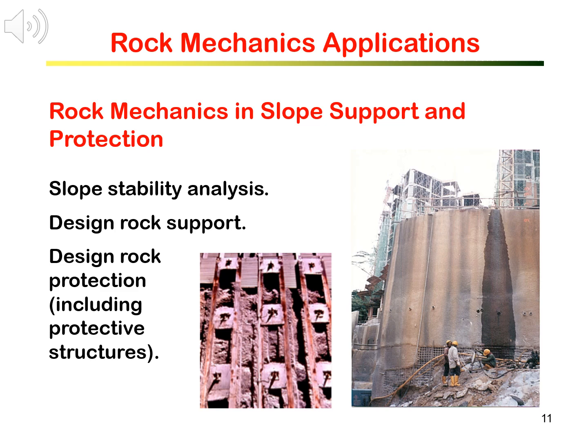For a rock slope to be stable and safe, the rock mass forming the slope must have sufficient strength to stand without any form of failure, particularly sliding along the existing rock joints. Here, joint orientation and joint shear strength play critical roles in governing the slope stability of jointed rock masses.